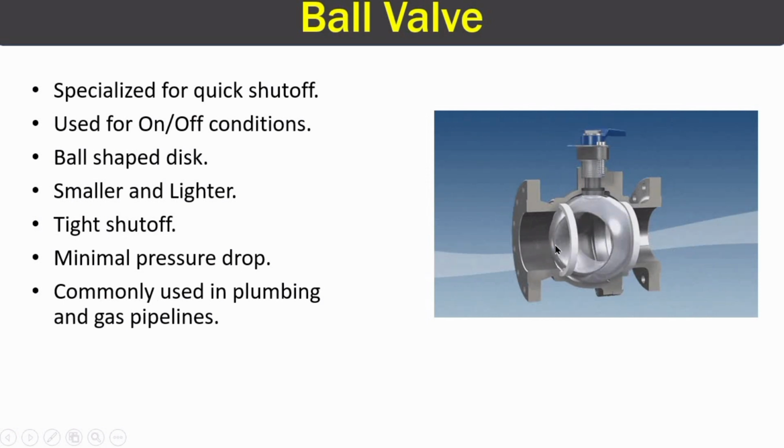Tight shutoff means when this valve is closed, there is going to be no leakage in the valve. And some other valves offer some leakages, like gate valve. Although when it's closed, it has some leakage still, but ball valve does not offer any leakage.